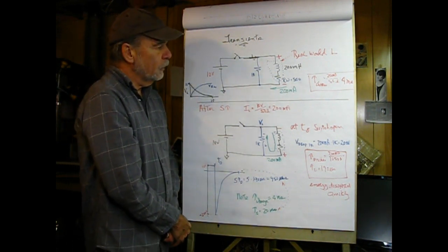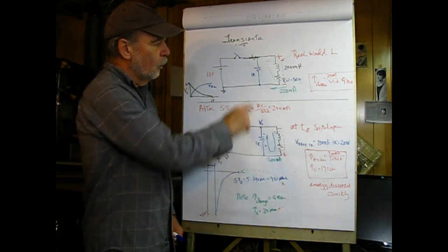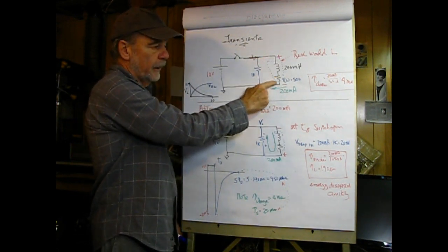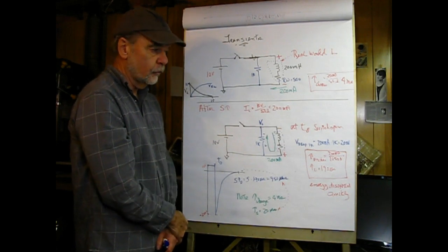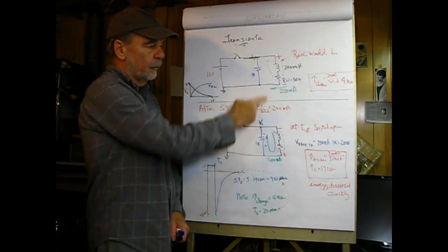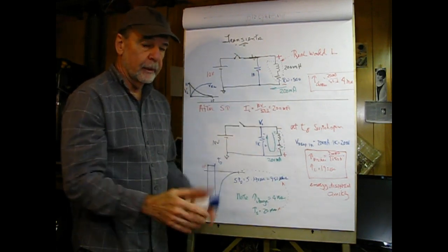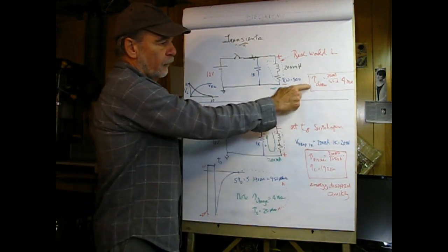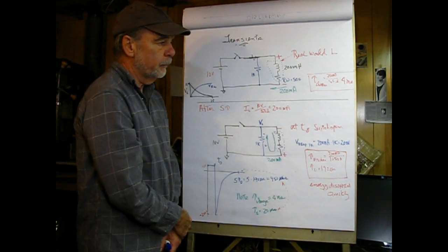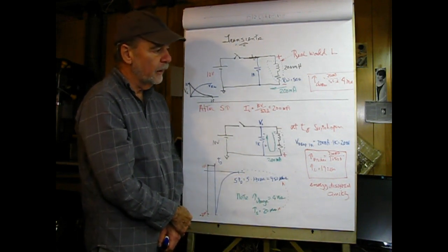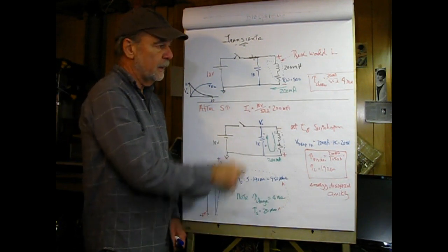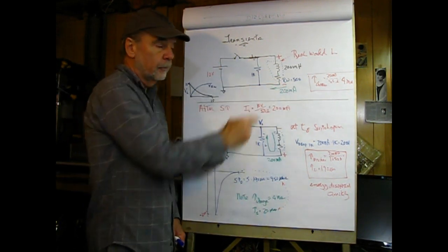So when we close the switch here, we'll examine the time constant for charging, and it's simply going to be the L in series with the winding resistance. A good example of this would be the core of a relay, which is basically an electromechanical switch. And what we see is tau would be equal to 200 millihenries divided by 50 ohms, which gives us a 4 millisecond time constant for the charging circuit.